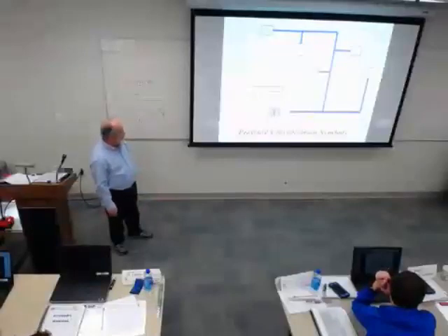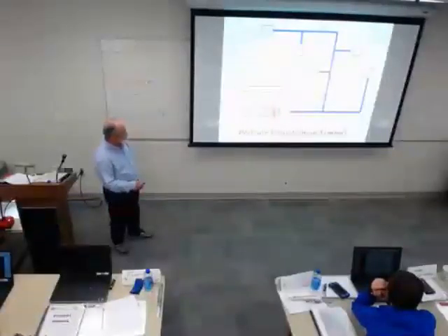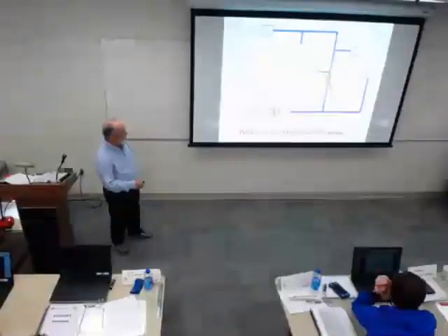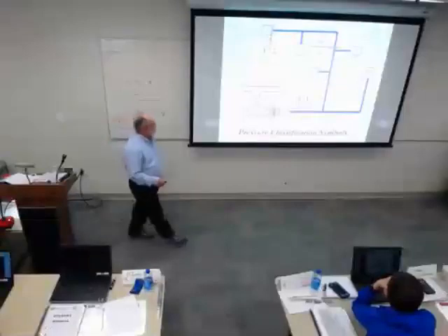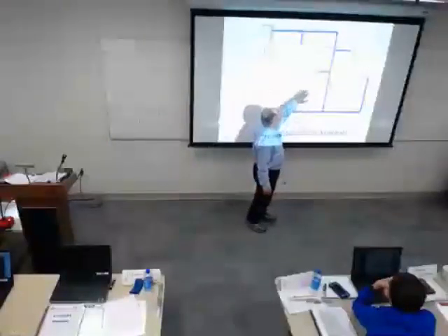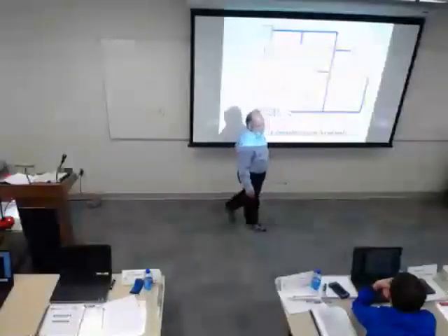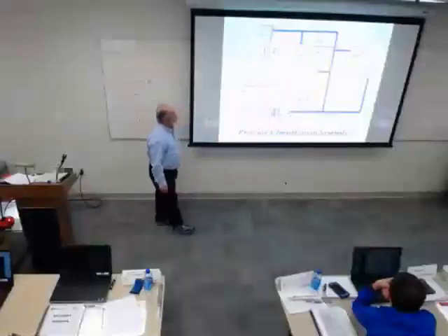All right, here we have a fan and a duct system, and on drawings, this is what SMACNA wants to see. On this side, we have a 4-inch class, then a 3-inch class that goes all the way to the place where it stops and becomes 2-inch, and then it goes on to where it becomes 1-inch.